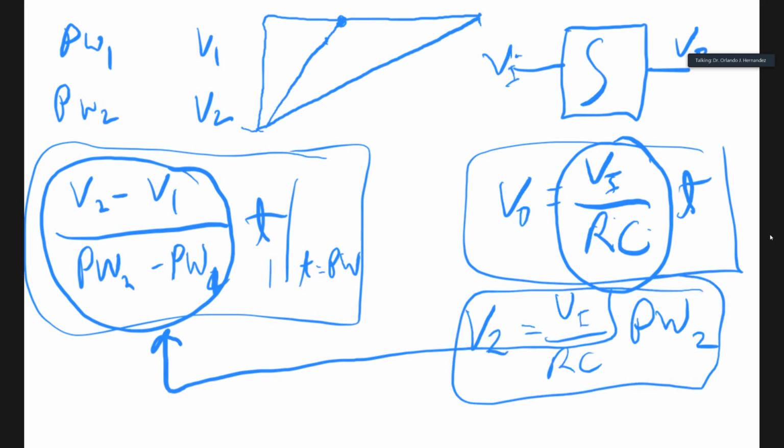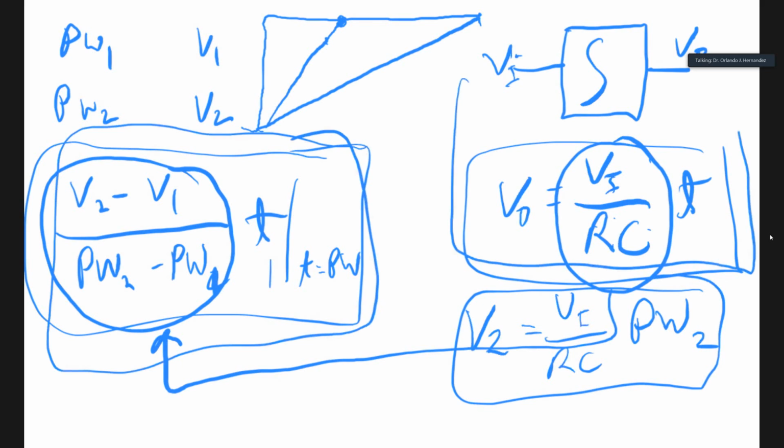So again, more specific to your project, but the same idea of system level derivation and circuit derivation. This equation comes from applying node analysis to the op-amp circuit, the classic Miller integrator. Okay? And just equating by inspection what the part that gives you the components value must be from a coefficient perspective in the system equations. And then you get your design equations and you find the values. That is what I'm going to want to see everywhere that is appropriate in 2 weeks. Then you can make it more sophisticated for the final report, but I want to see that you have done that work when you submit. Any questions about that?